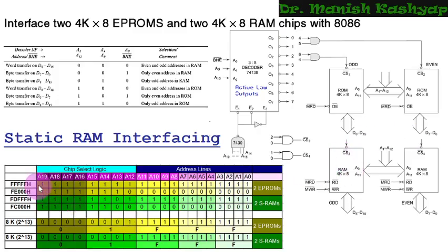Another important thing is, we discussed that bit numbers A14 to A19 will always remain 1. So if this is the case, then only this decoder should be activated. Otherwise, if there is any other combination from A14 to A19, this decoder should be deactivated. So you can see that A14 to A19 have been ANDed here, or rather a NAND gate has been used, since these are active low input pins.